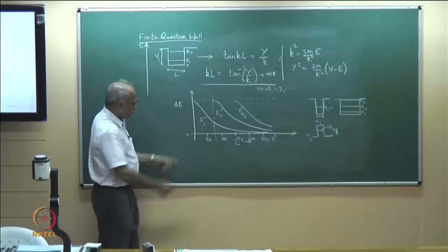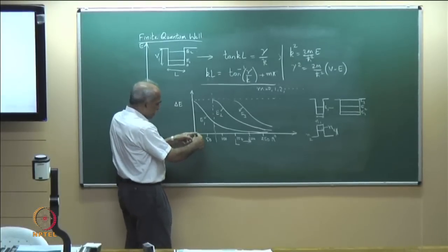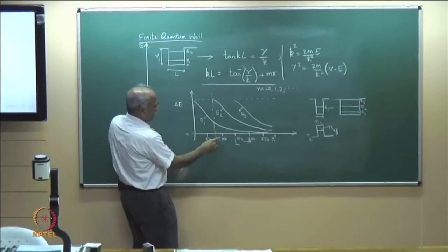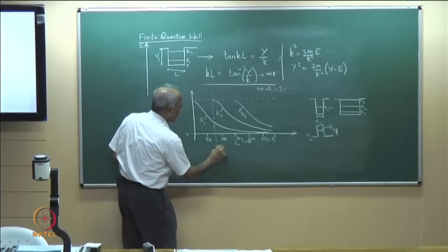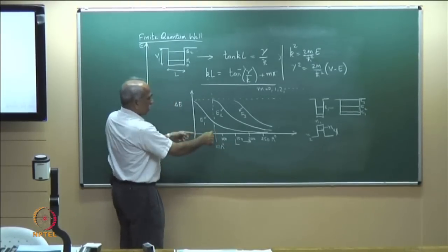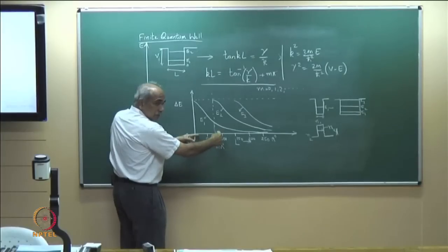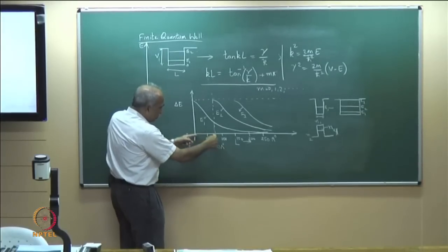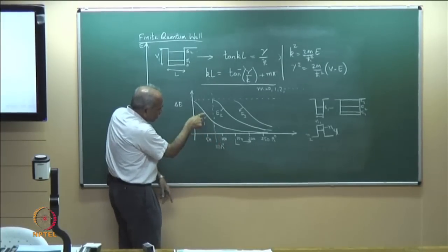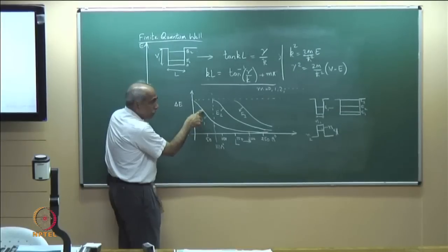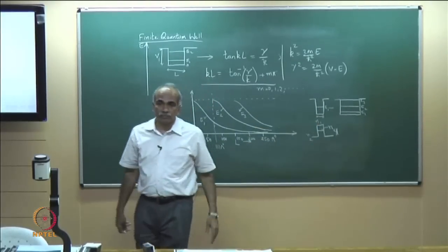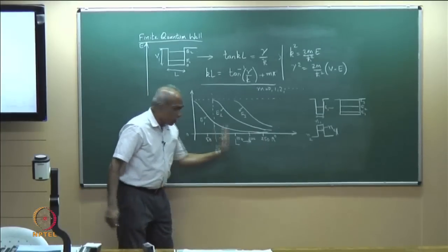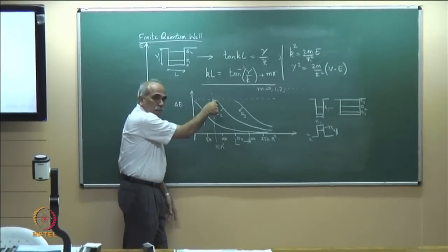So, what it means is, if from 0 to 80 angstrom, let us say this is 80 angstrom, I am just giving an example to illustrate the point. For all well widths from a small value up to 80 angstroms, there is only one allowed solution. There is only one E1, there is no E2, E3. If you cross this, then the second solution will come.